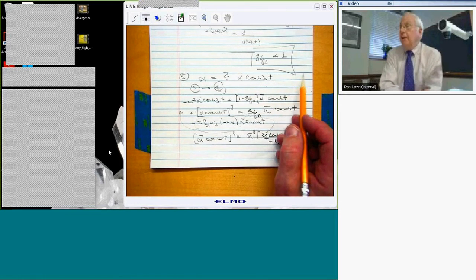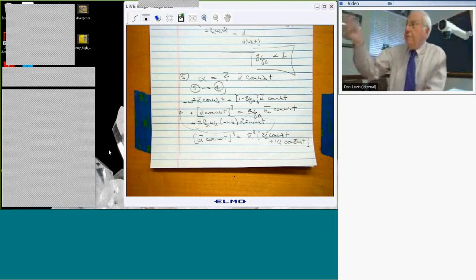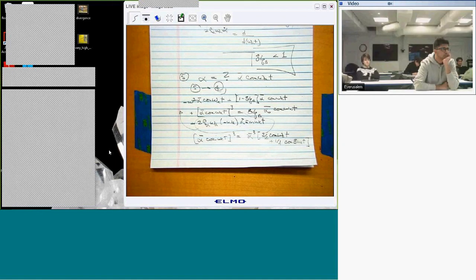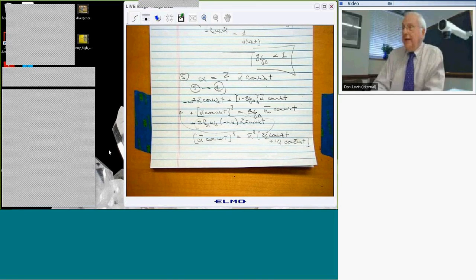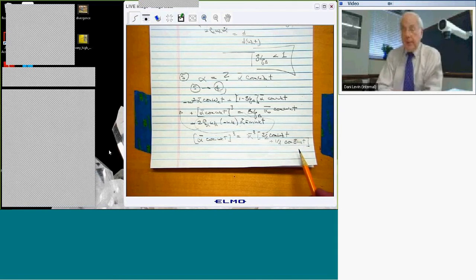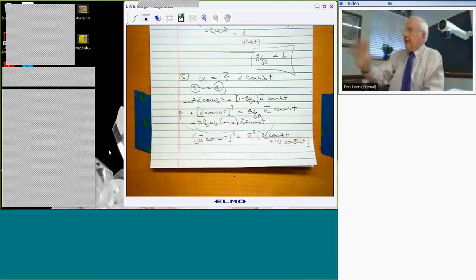But if I did that, then when I went through this, I'd end up with a cosine 5 omega_E t. See, I'm always one behind. So in the spirit of let's get on with it, we just ignore the cosine 3 omega_E t term here. But if we really like 3 omega_E t, we would put it back here and then ignore the 5 omega_E t term. You really like that one, you can see what happens, right? But at some point, you've got to neglect a higher harmonic in this method.